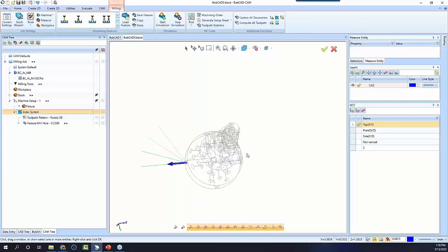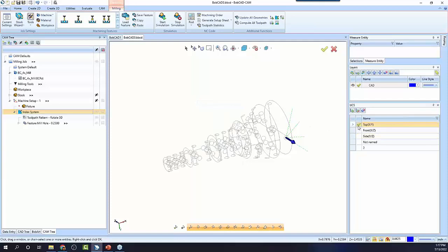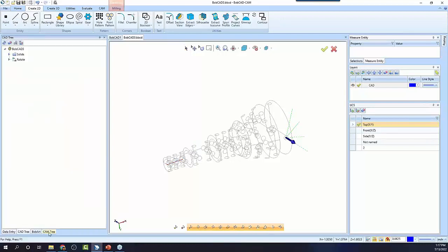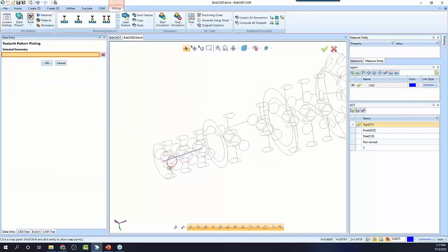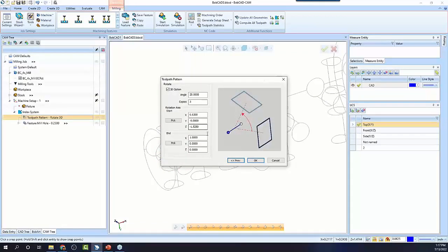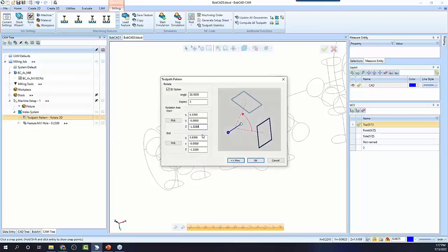Its axis. So what we need to do is pick a center line in order to kind of teach it what to rotate around. So I'll go back in this top UCS. I'm just going to draw a line. You know, it just needs to be on center. Okay. So we have that line, and this allows me to reference those point locations. So we'll say pick point, because it's not always clear to me what this value would be. So I like how I can pick these reference locations, and pretty much it's just the Z that we're trying to pick up here. Okay, so once we have that, you can see the Z value.